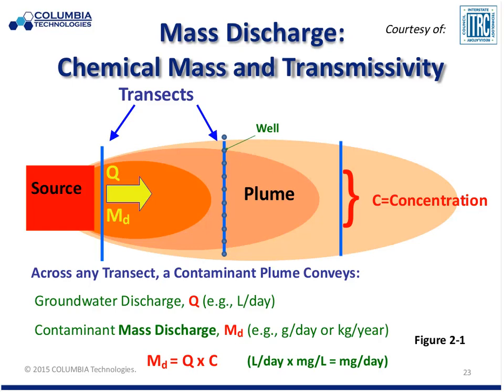That opens the concept that if I put these transects in, either with high-resolution tools or with my monitoring wells, assuming I get my monitoring well screens properly placed vertically in the right transport zones, then I can calculate a mass discharge rate going down gradient. I can get out of the business of estimating, well, we had a petroleum release at point A, and we've got a water body down gradient X number of feet, miles, yards, whatever, and if I put that in my groundwater modeling program using average numbers, then I expect it's going to take X number of years for that discharge to reach the water body. If you come back to the 10% concept, that's not going to be true because most of the transport is going to be occurring in that 10%. So finding that 10% with high-resolution permeability measurements and chemical measurements is critical.